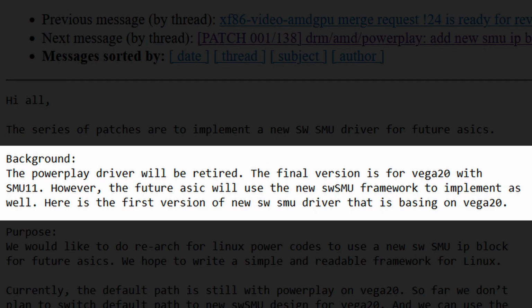As I discussed earlier in this video, since Navi 10, AMD has discontinued using the PowerPlay driver and moved all GPU power management functions to the integrated SMU. Unfortunately, we know very little about how the AMD GPU SMU works in terms of power management. AMD has not been very forthcoming with technical details on that topic. However, we can make a reasonable assumption that the SMU will read the VBIOS information at boot, store it locally somewhere on the GPU, and use that information then for power management.